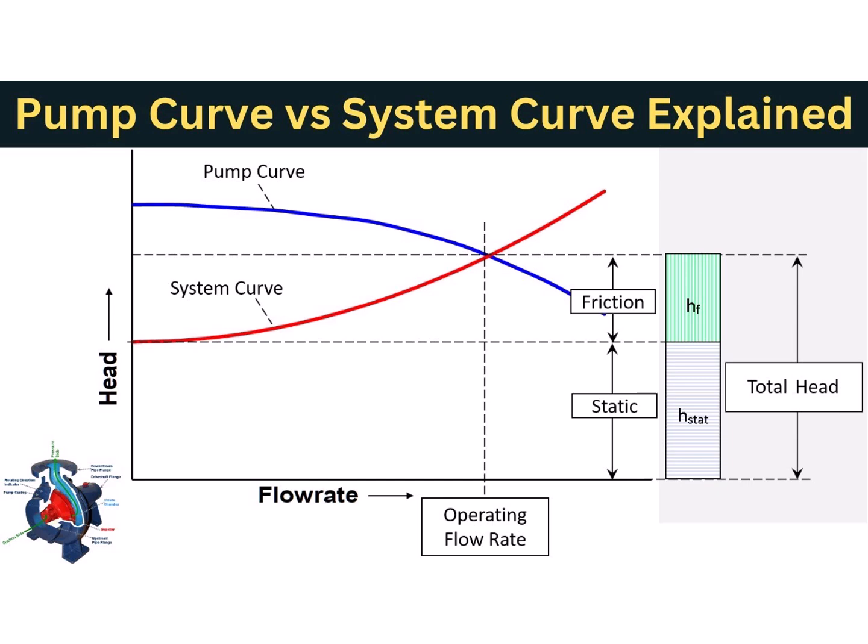You should make sure that at your operating flow rate, your pump efficiency curve is at the maximum, to have an efficient pump running with a long pump lifespan. Thank you.